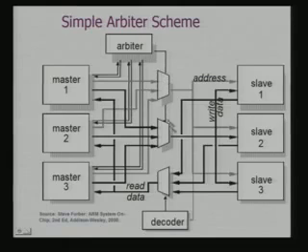Once it enables these buffers, the address flows from the corresponding master to the target slave device. First, the address goes. The decoder then knows which slave device is to be enabled and targeted to receive the data. Each slave device is provided with an address, and using that address, the master refers to the slave device.